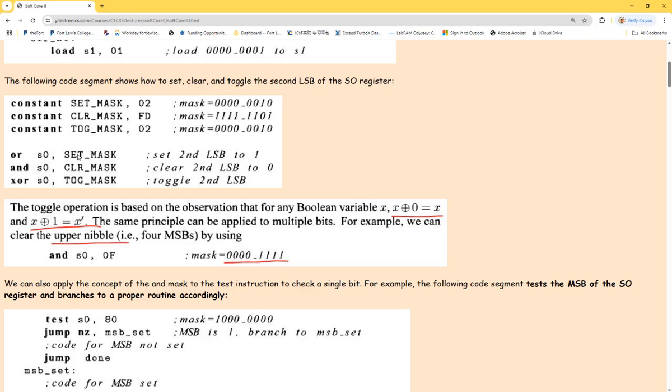If it XOR with 0, it's not changing that bit, right? So for question number 1, it should be an XOR operation with a certain mask, targeting that bit 5, and eventually it will update S0 itself.